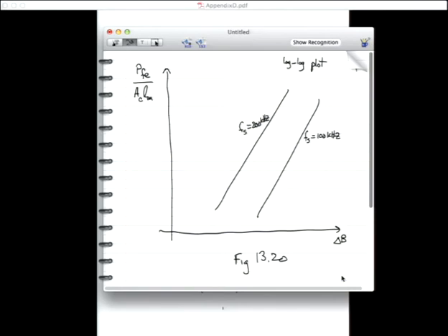So what you have to do really is, I guess there are two ways to approach it. One is you can simply calculate your delta B, and if you know the frequency, then just use the plot and read the value off. That's a perfectly good way to do it. Another way is to use the formula, and we had a formula that was PFE equals KFE times delta B to the beta exponent times the volume.